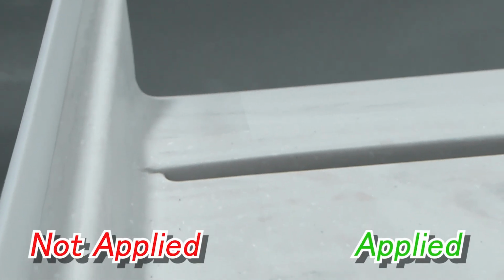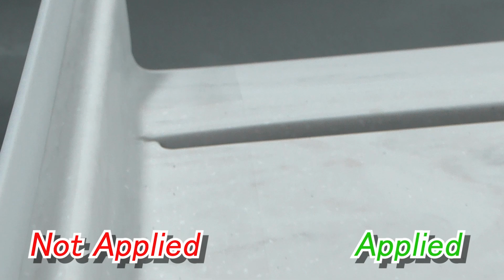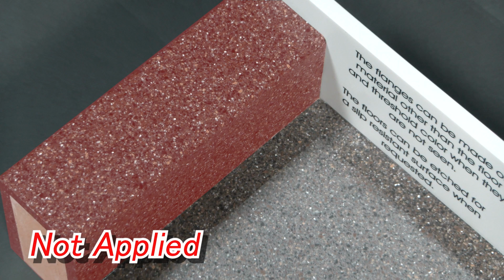With sloping or ramping entry point variations, the slip-resistant finish remains roughly 2 inches from the wall, but runs all the way through the entry to the exit of the shower pan. This is because these entry points act almost as an extension of the floor, rather than having a direct threshold divider such as no drip entry.